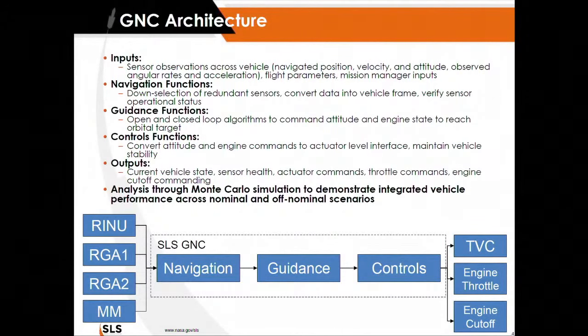And we do a lot of Monte Carlo simulation with this, where we have this block here implemented in a big 6-DOF simulation, and we'll do Monte Carlo analysis to assess sensitivities, performance, all that kind of stuff, to verify that the design for the sensors and our software here matches the requirements for the various scenarios.